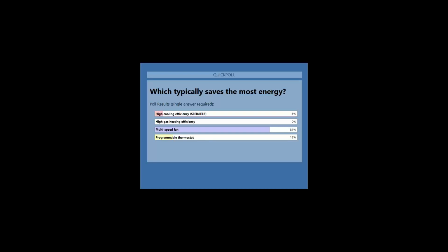But instead of making them the same size, let's say you had a 10-ton unit, instead of buying 2 5-ton compressors, maybe I'm going to buy a 4-ton and a 6-ton. And I can run compressor 1 to get 4 tons of cooling, or I can shut that off and run number 2 to get 6 tons of cooling, or I can run both of them at the same time to get 10 tons of cooling. So that's kind of a unique way to get more stages of control. More is better in this case, without having to have more cost.